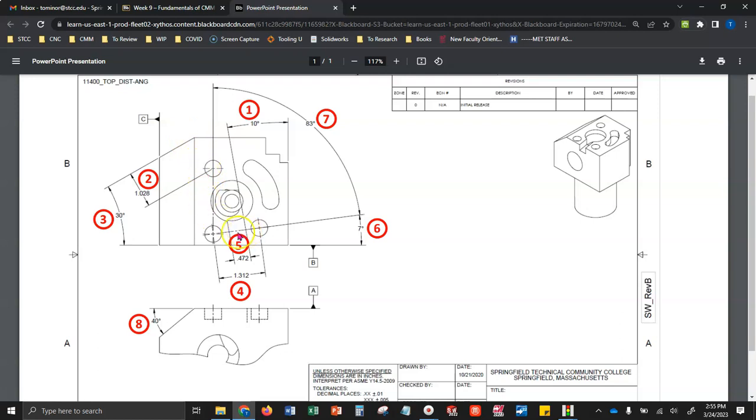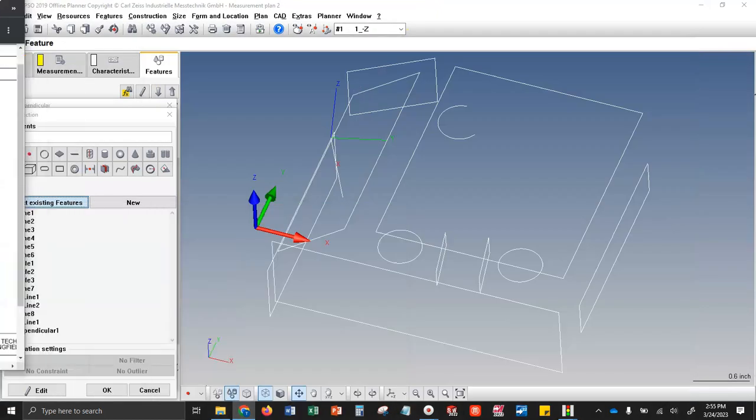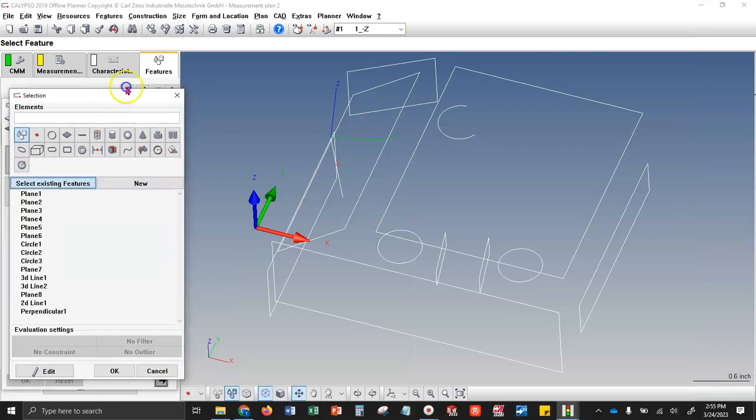Over here, if we select this surface first and that one second, the arrow will be shot from the second surface to the first. If we did the reverse, we selected this first and that second, the arrow would be shot from here over to meet there. So in applications where the angle between this and this may change, just be careful about the order you selected in.